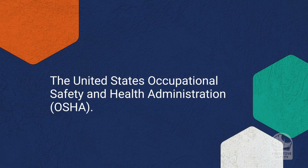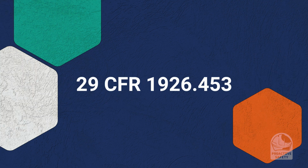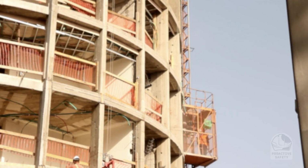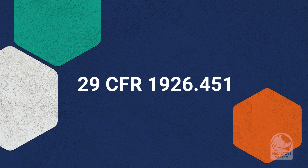OSHA standards. The United States Occupational Safety and Health Administration, OSHA, establishes specific rules and regulations for the use of lifts and aerial platforms to ensure safety in the workplace. Some of the OSHA standards related to lifts and aerial platforms include 29 CFR 1926.453, General Requirements of Elevators and Hoists. These standards establish general safety requirements for elevators and hoists used in construction, including inspections, load capacity, signage, operation, and maintenance.